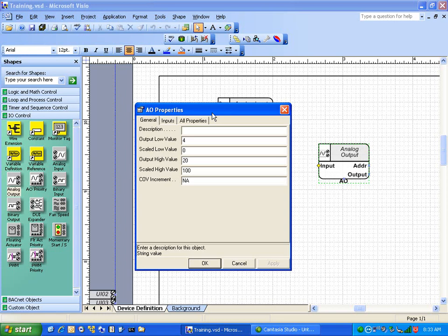Typically, when I do valves and dampers and fan speeds and pumps and things like that, I'll use a COV of 1. We really don't need to see a fan speed at 20.2, 20.3, 20.4. If it's a bigger, busier job, you can even go a little higher if you want. You can go 2 or 3. I have some jobs that I've gone that high just because I know there's a lot of pulled objects going on. So I'll even do a pump speed or something with a COV of 2 or 3.